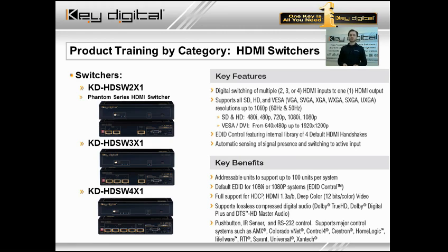So whether this is being used for a residential installation, where you might have your common standard and high definition 480i, 480p, 720p, 1080i, and 1080p resolutions, or whether this is a computer application where you may have any of your VESA type resolutions all the way up to 1920 by 1200, the Phantom series supports those resolutions without any problems. And additionally, Phantom series offers EDID control. These switchers are controllable via IR, via RS-232, and of course via a push button control on the front of